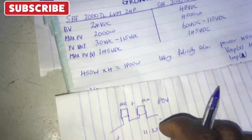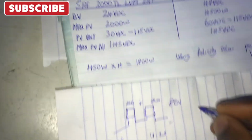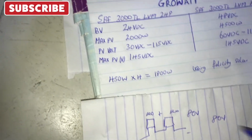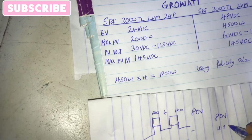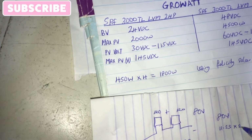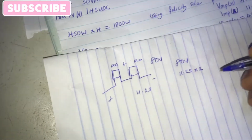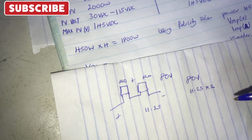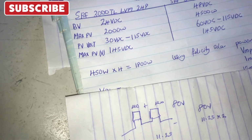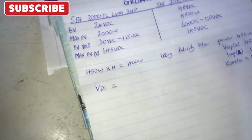When you have another 2 panels, then you parallel the 2 of them, connecting positive to positive and negative to negative. Voltage will remain 80 volts, while the amperage is going to be 11.25 multiplied by 2, because voltage is constant while amperage will increase, because we are doing parallel. We've covered this in our last video, which I will leave the link in the description, so I just want to do it a bit fast.